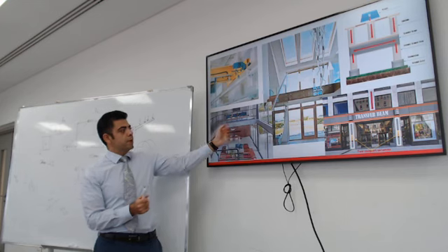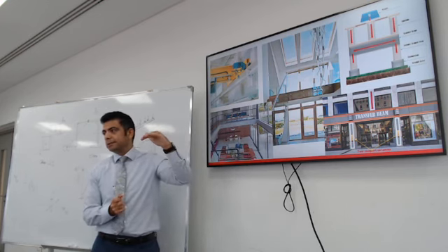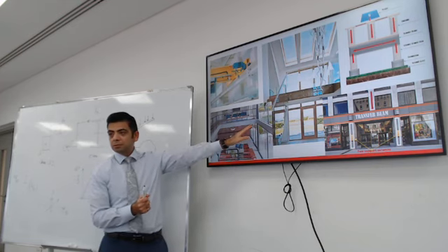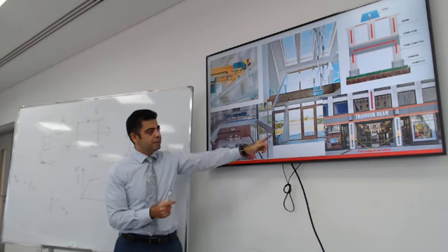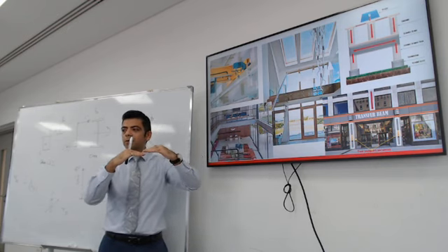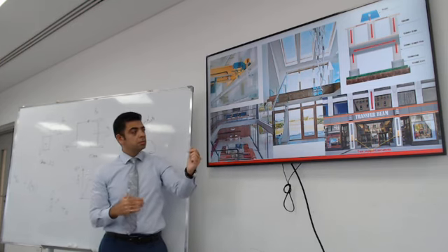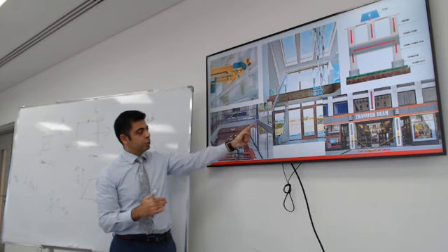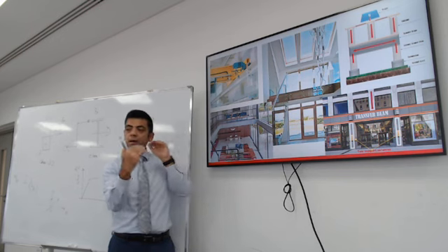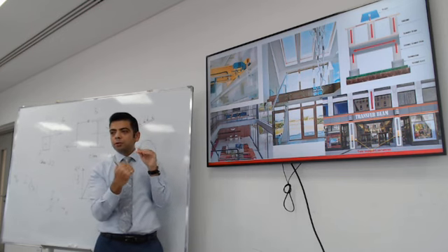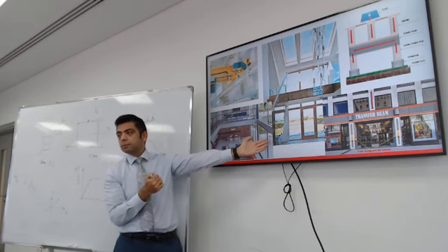Is this beam laterally restrained or unrestrained? The column. Interesting. Okay, so let's think of this beam. Is this beam laterally restrained or unrestrained? What is restraining this beam? The other beam. Yes, over here. So it's restrained here. What about along the beam? Is this part restrained laterally or unrestrained? Depends if it's one restraint. What do you see? This is a window. It's one beam.